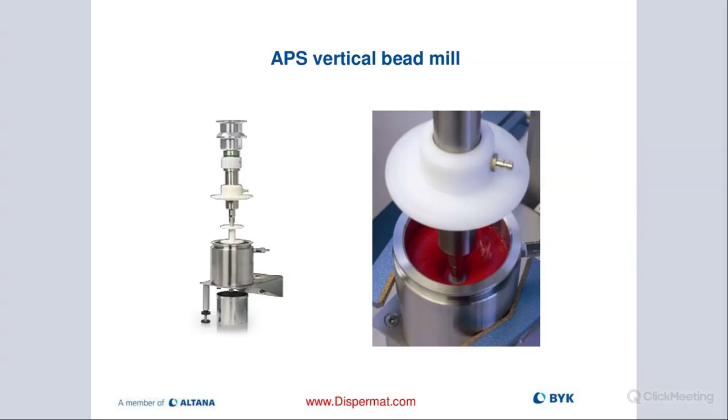We only would then eventually dump out the beads into a container and take off the milling disc and run it through a sonic bath for a few minutes, and that basically cleans everything. So very easy to handle and perfect for a laboratory environment, R&D setting, but not scalable. There is no large production versions of this available.